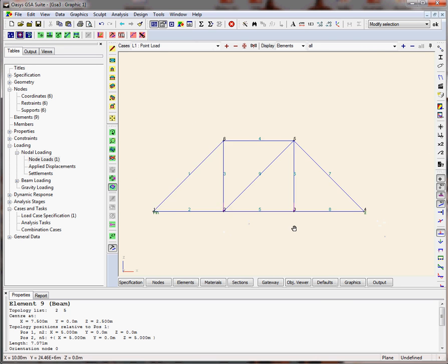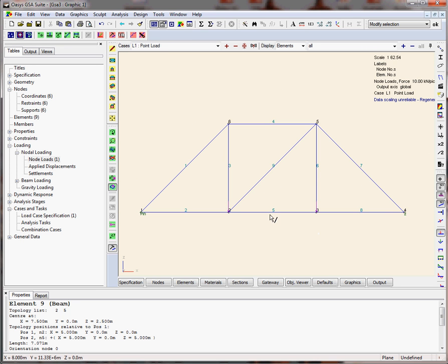And if we wanted to display the values of loads that are being applied in these locations, you can click on select var annotation and just hover over the 2 arrows, and you'll see that it has a value of 10 going downward, and as I mentioned before, positive Z is going up. That's why we input a -10 in the table when we're defining the loads.